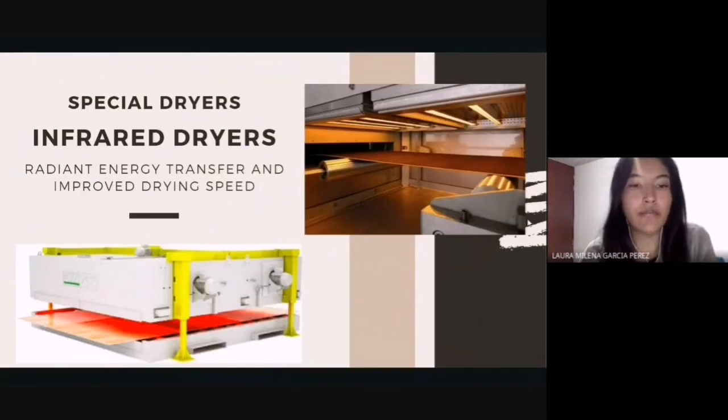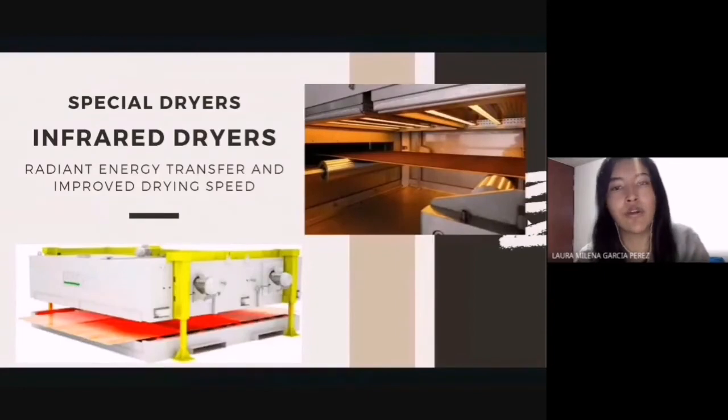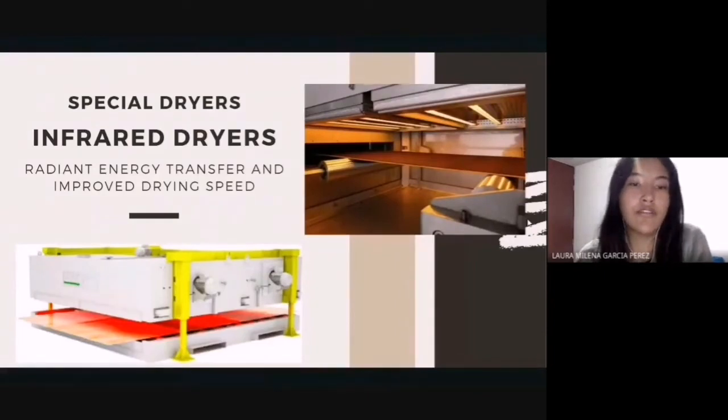Infrared dryers can produce much higher levels of heat flux, that is 4 to 12 kilowatts, than the other dryers. However, in many drying operations, a high heat energy is not required. There are some specific applications for this type of dryer in certain industries, for example, in the drying of coated paper. These dryers offer the advantage of compactness, simplicity, and low equipment cost. Additionally, they offer potential for significant energy saving and improved drying speeds with a better quality of the product.